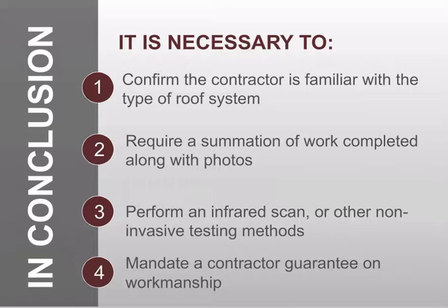In four, we want to mandate a contractor's guarantee on workmanship. Very important. This is one of those things where I think the first word in that statement is huge. We want to mandate that, because if you don't ask for a contractor's guarantee on workmanship, typically you're not going to get one, especially in a repair scenario. We see all the time owners investing $5,000, $10,000, $50,000 in roof repairs, and they're not getting any sort of guarantee from the contractor that it's going to work.